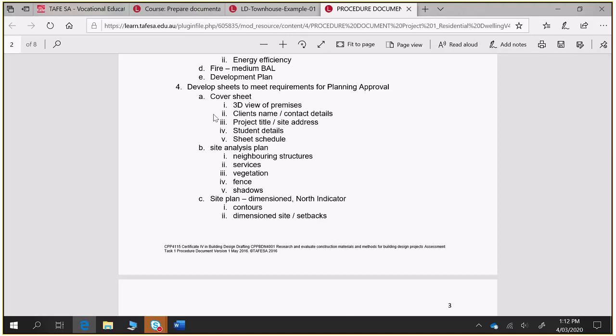So typically what I really like and what I do is I provide separate figures: a floor area, then carport area, and then veranda areas and porch areas. Separate them out like that. The main reason I like that is the work that I used to do for the state government was determining what's called an equivalent area for a building. All your rating and taxing isn't done on the actual size of your floor plan, it's done on equivalent area, whereby the area of your floor plan counts for 100%, and then your porches and verandas are 25%, 33% of a carport goes on there, 66% of an enclosed garage goes on there, etc.